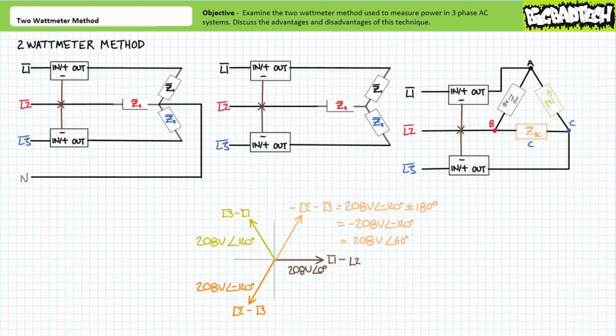in the system by keeping a hand on 2 lines, i.e. the 2 line current ammeters, and a foot on the other, i.e. making use of the other line as our reference. With 3 points of contact, the truth can be squeezed from this system. Note the 2 wattmeter method is entirely external to this system. It works for either Y or delta configurations, and for damn sure it's a lot easier to implement than the